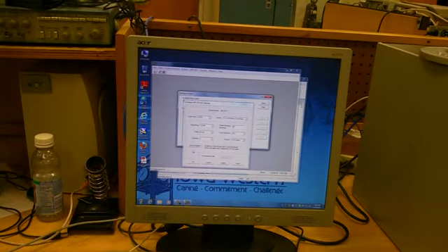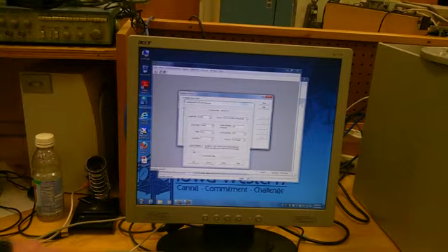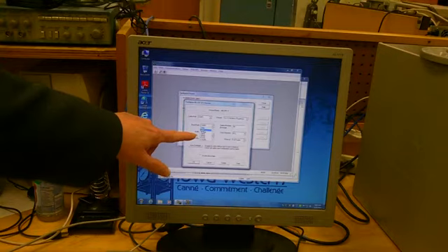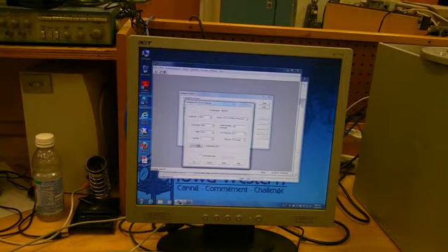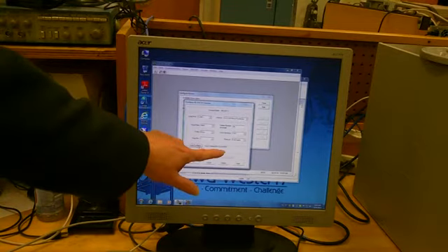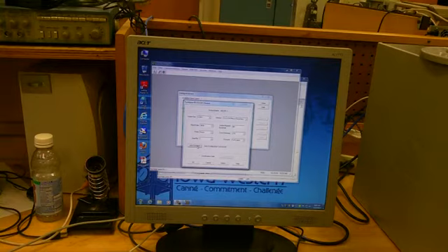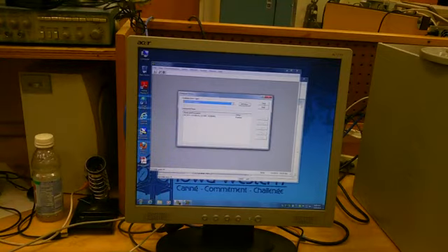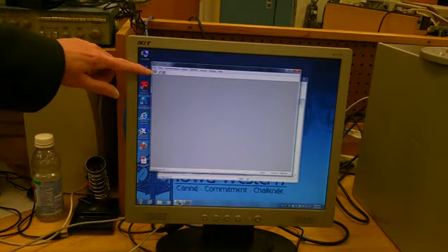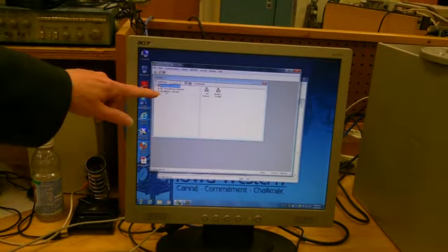This one's in run, so we're going to do it again, but we're going to drop the baud rate down to 9600. Click, and then try it again. And right now it's saying auto configuration successful. What that means is that we are now talking to the unit. So we can say OK, OK. We can close.